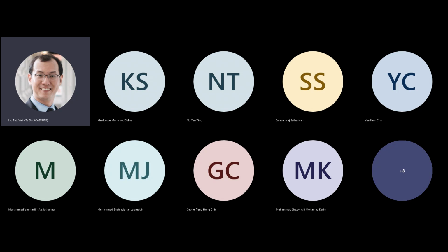Because the switching of a logic gate can be interpreted as the charging and discharging of the capacitance at the output of the logic gate through the effective resistance of the PMOS or NMOS. So that's where we're going with this.